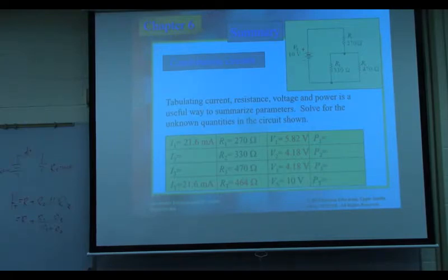Look at this here. We will find the current. Then what's the next one? Current. Find the current. As we said at the beginning, we can use the current divider, but that formula looks lengthy, right? So here, look at this. We know the voltage, we know the resistance. Can we find the current? Yes. What law? Ohm's law, right? Use the voltage divided by this equals this one. 12.7. This one divided by this, 12.7. Yes, that's close, right? That's possible.